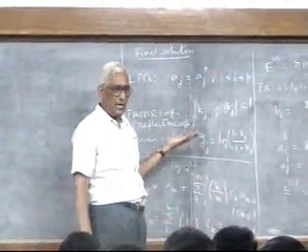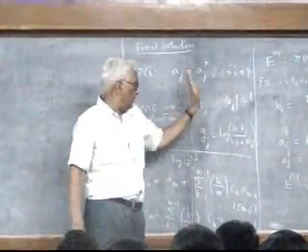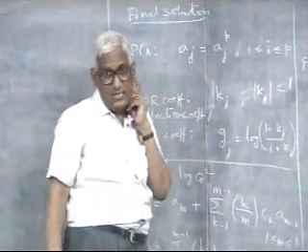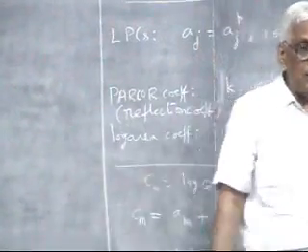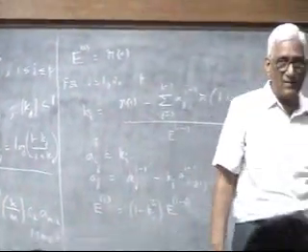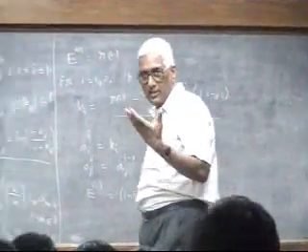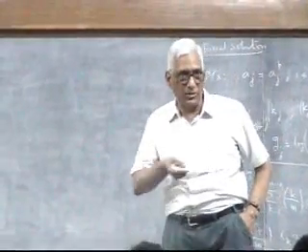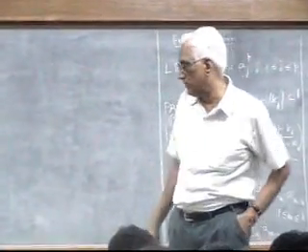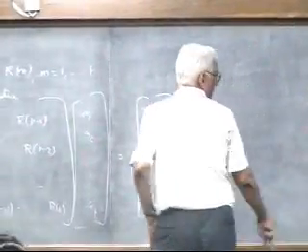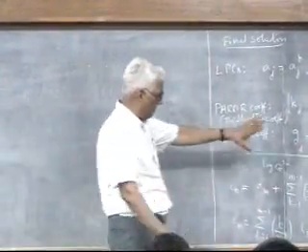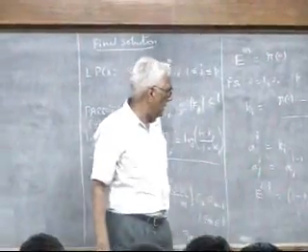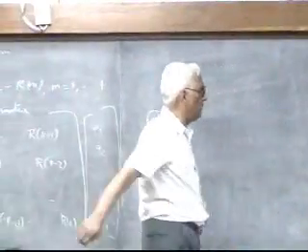And as I told you, we should keep that aside. Two things I wanted to bring out. One is that you will get what is called the k as an intermediate result, which is called a PARCOR, and E helps you again to monitor that the error comes down as you keep increasing the order. This algorithm needs you to be a little more careful here. I have written it correctly, but the interpretation needs a little care.